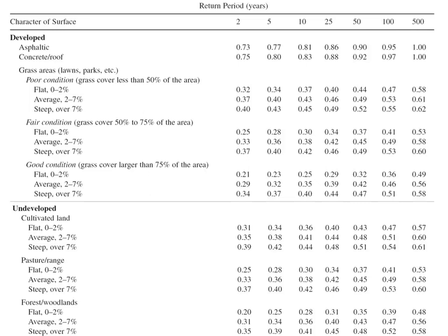So sometimes that's hard to know, should I use forest or pasture? You know, how many trees does it take to transition from a pasture to a forest? Doesn't look like the effect is too dramatic, you know, 36% versus 34% for the 5-year storm. But these C values are the biggest weakness of the rational method. The hardest thing about applying this method accurately is picking a good C value.